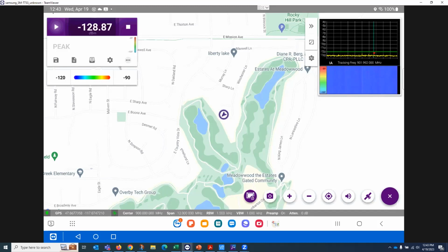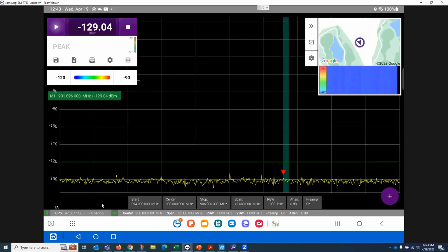But just a little bit about what the tool looks like. In this case, I have set this up to keep it fair to everyone. I'm using 900 megahertz as my uplink because I don't want to pick on any one service provider and throw a bunch of stuff in their uplink, because I am going to generate an interfering tone through a setup I have here. So I'm picking just 902 as the frequency, just to be fair to everyone, right? That's not fair to any one provider.